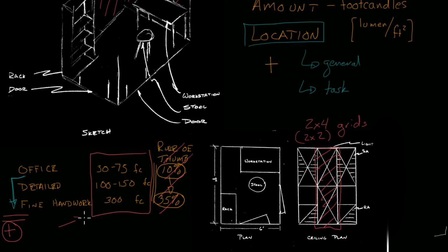In real projects, you need to calculate the number of foot candles at the space, which is a function of, say, things like the wattage of your light source, the density of your light source. How many of them do you have? It's also a function of the height of the workspace. How much of the light reaches the workspace? This is a question of focus. In addition, you have to think about the heat of the light source. This is going to incur additional load on your HVAC system.